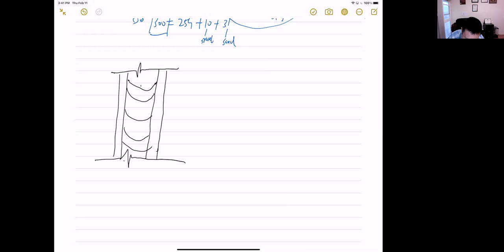So for concrete inside the core, it is under a situation similar to what we just discussed. Okay, three-dimensional or triaxial loading. Vertically, it is under compression. Horizontally, it is confined from all directions. Okay, because we have something like this. The rebar is confining the concrete from expansion horizontally. If that's the case,